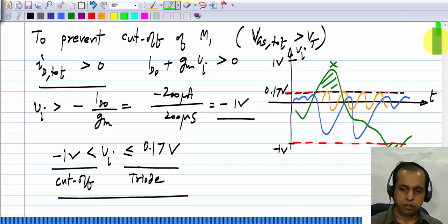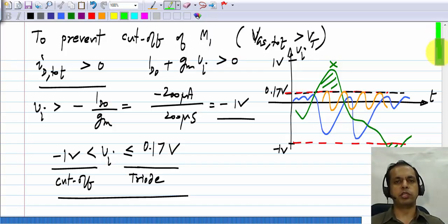So far all our analysis has focused on the small signal picture, but the swing limits do very much depend on the operating point. We had many options, right? Different kinds of biasing and different values of quiescent VDS, VGS, etc. that could be chosen. So far we would choose them arbitrarily, but now we know their role. They play a role in setting the swing limits.